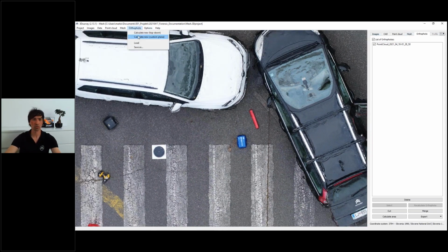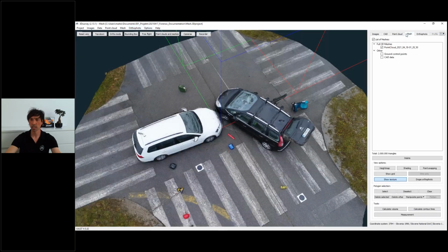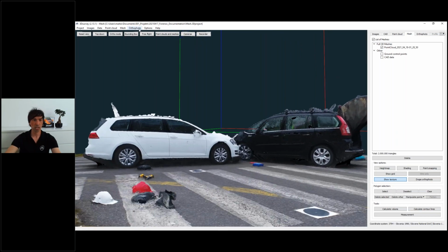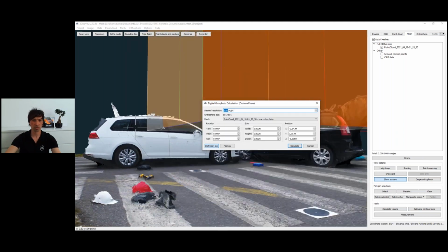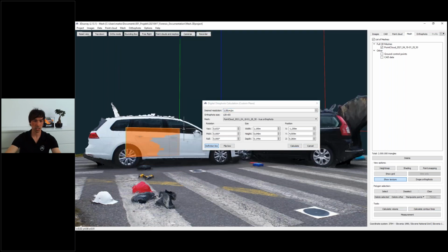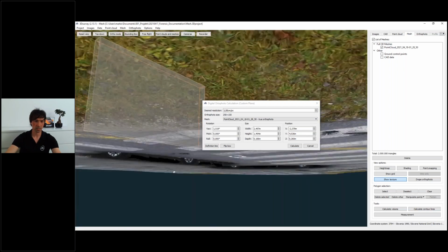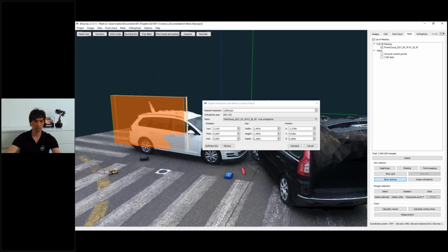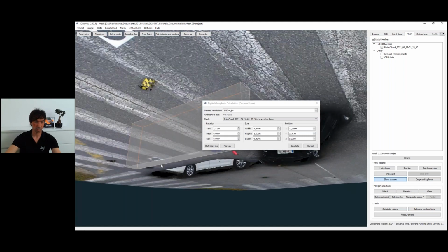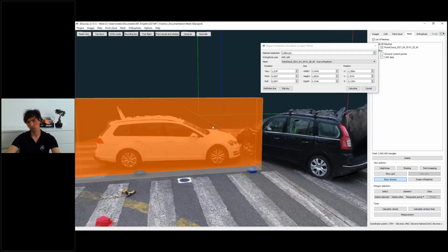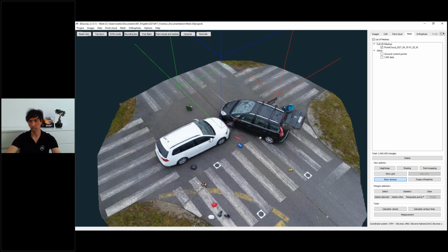Here is also an option to generate a side orthophoto. So in case you would need to generate something like that and put it in 2D, you would use this custom plate orthophoto and actually define your side plate in this way. For example, I'm using the right mouse button to extend the planes under it like so, and in this way export the side orthophoto. Feel free to try it out by yourself. It's super easy, works really nice.